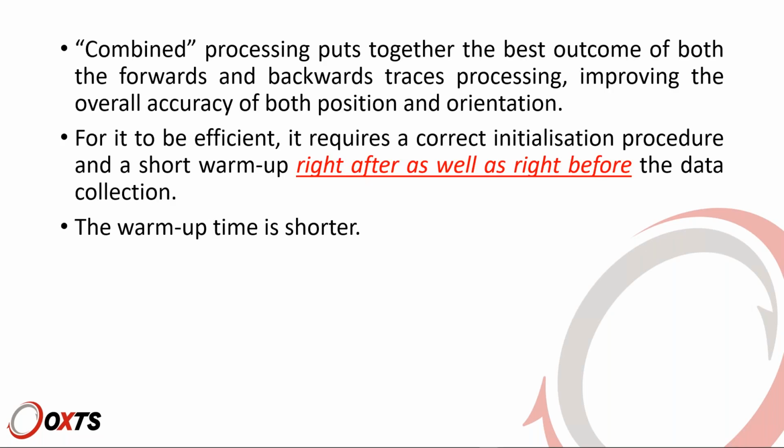Combined processing puts together the best outcome of forwards and backwards traces. So it has an overall result that will be better than each of the two traces separately taken. It will help your position and orientation, attitude, position accuracy. If you have in mind to use the combined mode, keep in mind that the backwards trace will have to initialize and warm up as well, the same as the forwards.